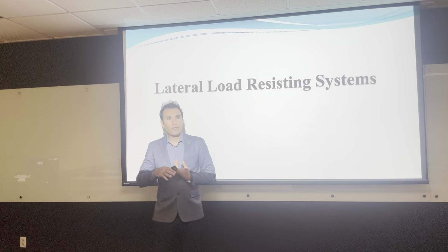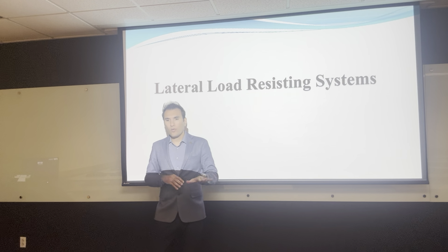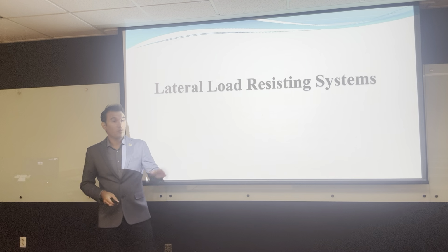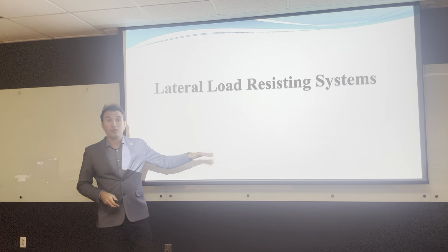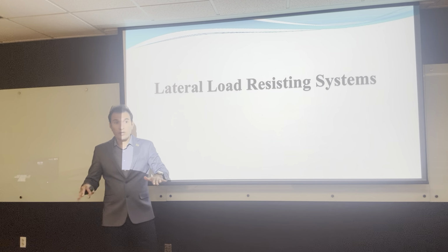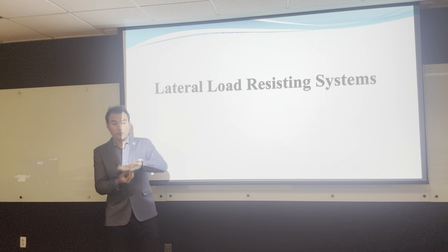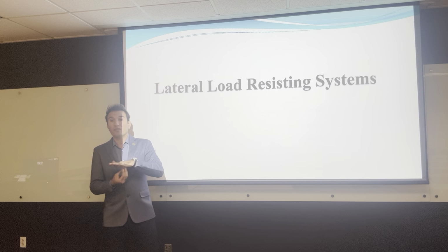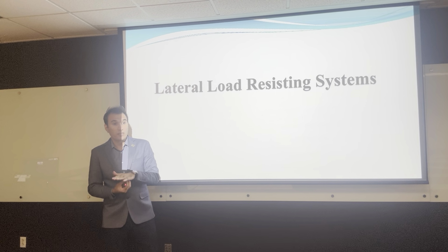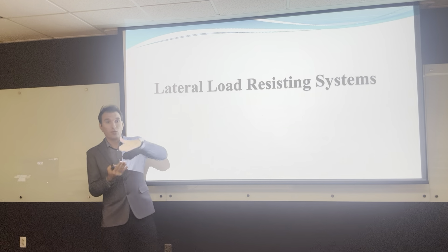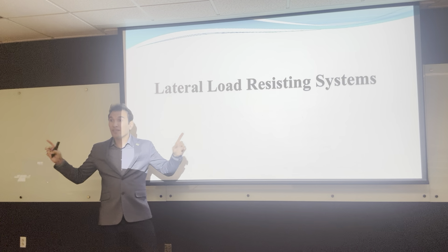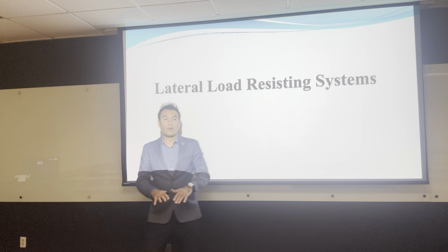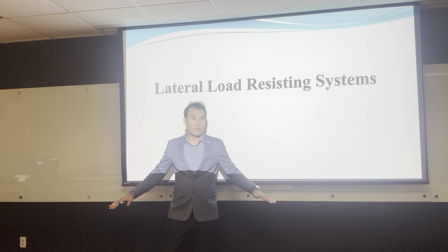But what we have been navigating over the last few lectures is the gravity load resisting systems. We talked about flat slab. Do you remember when the slab rests directly on the columns? We talked about the solid slab, when the slab rests on beams and the beams transfer to columns, that's called the solid slab system. There are waffle slabs, ribbed slabs. All these are called gravity load resisting systems.